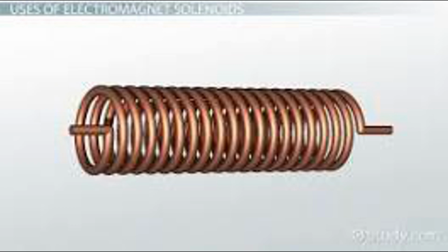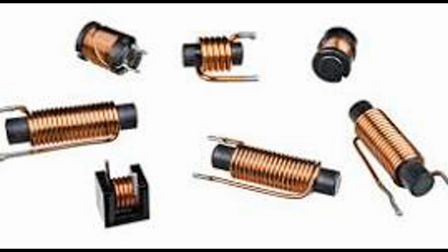3. Frame or housing. Material: often made of metal or plastic. Function: the frame provides physical support and protection for the internal components of the solenoid. It may also help to concentrate the magnetic field and prevent interference with external components. In some designs, the frame also helps guide the movement of the core, ensuring smooth motion.